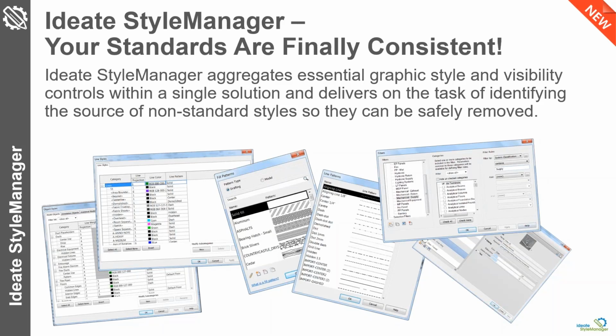This content can contain object styles, patterns, line styles, all kinds of standards, or I should say not standards, but really styles that are going to start to, for lack of a better word, infect your Revit model in the sense that they're not going to match maybe the standards that you have set forth or desire. So StyleManager is allowing you to review all this information, all these different styles, and then make educated decisions based on the analysis of that data.